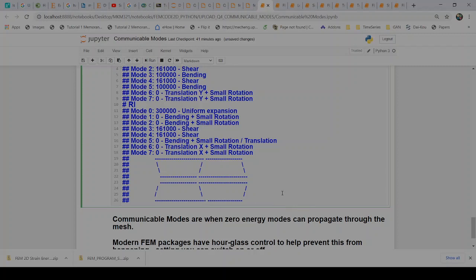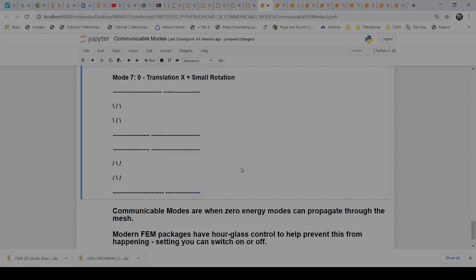What I'm trying to tell you is, the beauty of this is, I can deform a Q4 element, these 4 elements, into this shape. When I have reduced integration, there is no strain energy associated with this kind of deformation. And I know that doesn't make sense, because when I take that mid-side node and move it around like this, you'd expect to see lots of strain energy associated. If you have a piece of steel and you're trying to move points in that steel so that things in the deformed shape look like this, there will be lots of energy associated with that. But the reduced integration sees no energy associated with that. And that is the issue that we have. So this is not going to work.